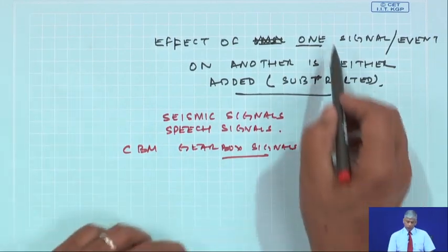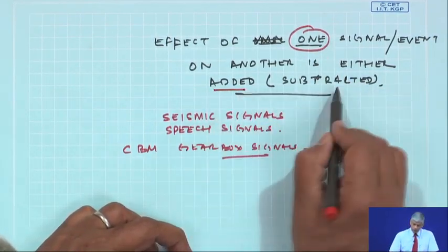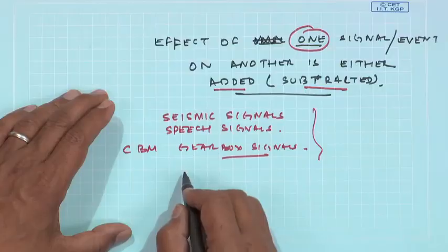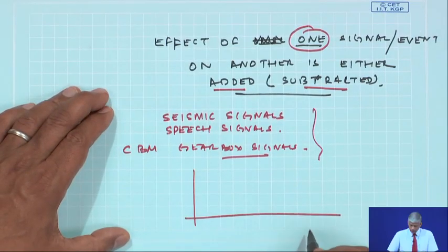Now, because this is added or subtracted, I can very easily separate the sidebands by doing a Cepstrum analysis of such modulated signals, and as you will see later on, modulated signals do occur in gearboxes, and once we have the Cepstrum, they will look like this, which is known as the Q frequency.